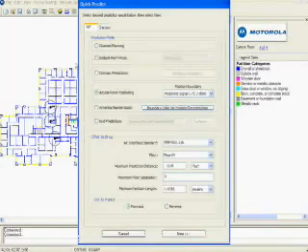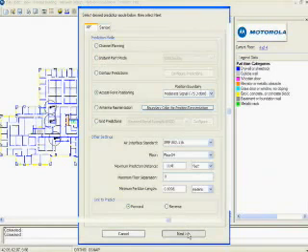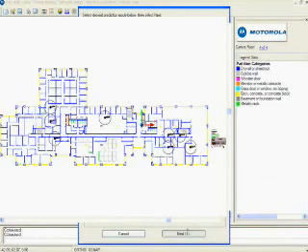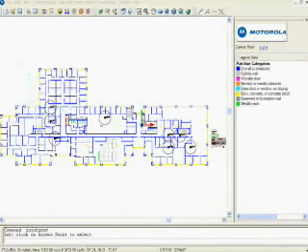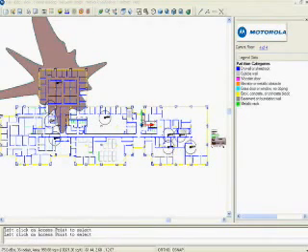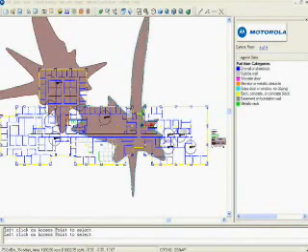Sometimes it may be necessary to move equipment due to mounting location or wiring restrictions. Here I'll show you a real-time network simulation that allows us to pick up an access point and move it in real time. We'll look at the negative 75 dBm signal boundary. I use the mouse to select an access point, and I can begin dragging and moving it around inside the facility. You see the coverage contour update and fluctuate in real time to show you the coverage boundaries of that access point. Once we've selected a good spot, we can drop it, and that area will be shaded in.